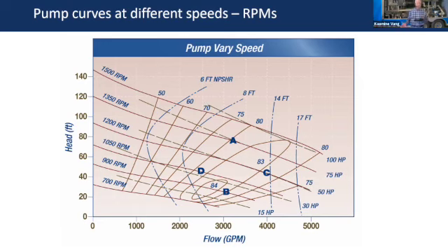And you can buy a soft starter if all you need is a soft start cheap. Most people, the VFDs are not that much more now than soft starters, so they buy this. Maybe they're a little bit more, but they buy a VFD because it gives them other options. Maybe they don't need full speed all the time. At my farm, my little 20 horsepower pump runs full speed, irrigates the whole field at once. If I put a VFD on, it actually costs me more money, not to mention the cost of the VFD. I have no reason to slow it down because I irrigate everything at one time. So it just depends on your application.